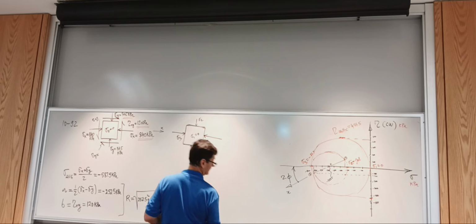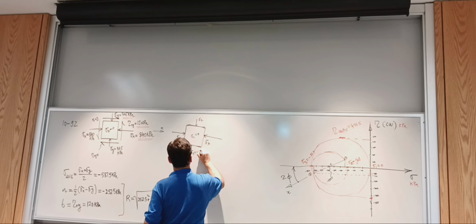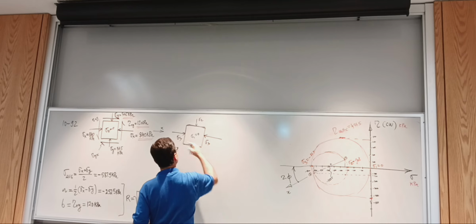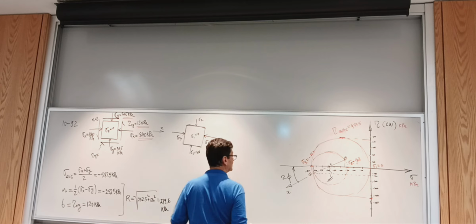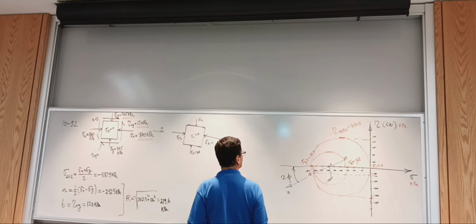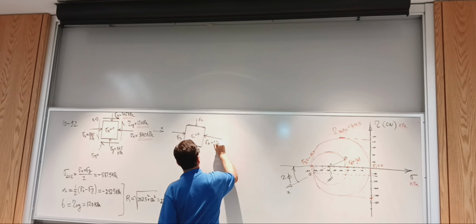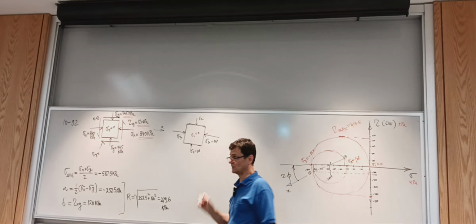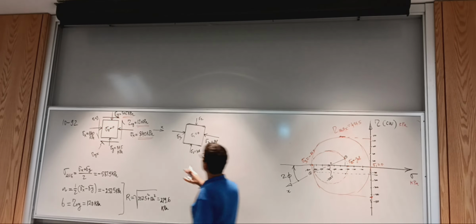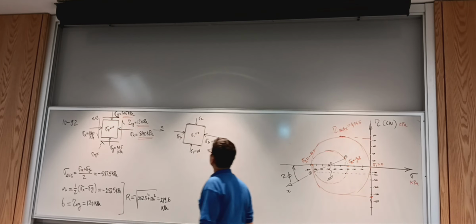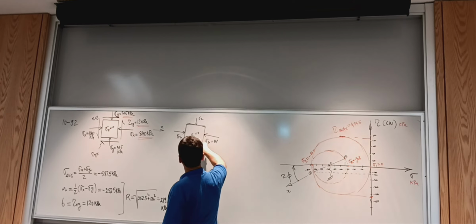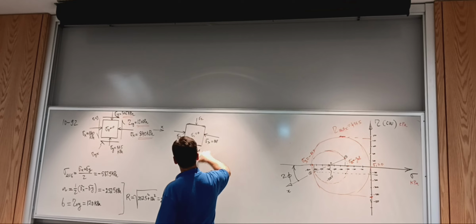So we get negative 308, or 308. The orientation of the arrow tells us that's compressive, and this other one is 867. Both compressive. All right, so this is the principal element. It does not have shear stresses. That's part of the definition of the principal element: there's no shear, and these are maximum or minimum.